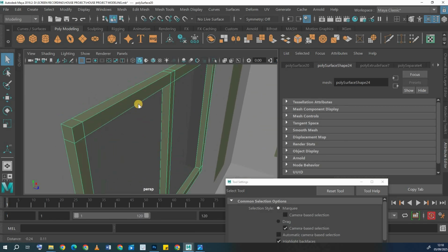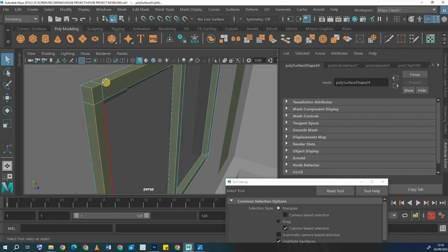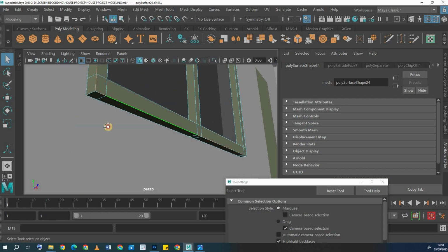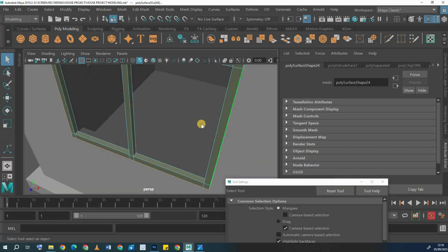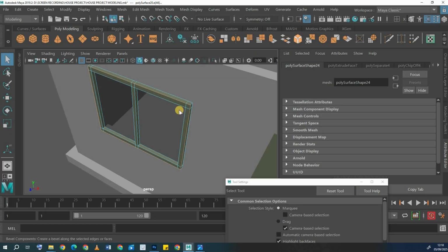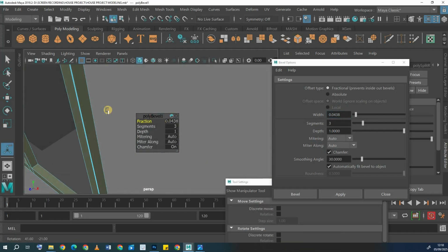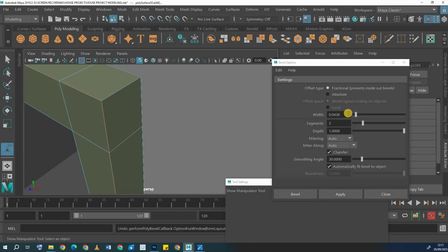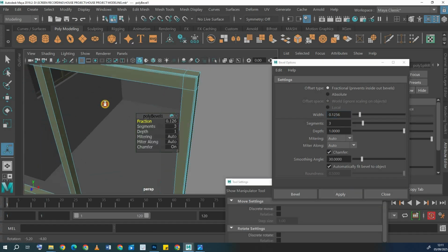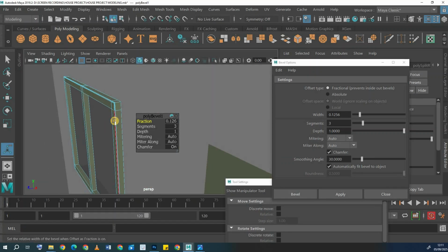If you want, you can do smoothing on the edges. If you want your windows to be even nicer, have a nice house, you can do smoothing on these edges by selecting the line, then do bevel. Remember that? Yeah, you can do bevel. It's not enough. You can increase the width and do bevel on your frames, and then you can also do it to the side.